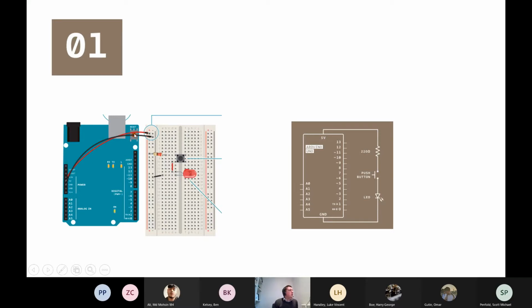It's just worth noting some details on the left-hand side. The Arduino has a whole load of things we can connect up to, and here the connections we're using are one called 5 volts and one called ground. So we're using our Arduino a bit like a battery there. We're getting some positive voltage of 5 volts and some 0 voltage, or ground. You can see that's in a section of the Arduino that says power next to it, so the Arduino tells you what each of these connections is going to do.